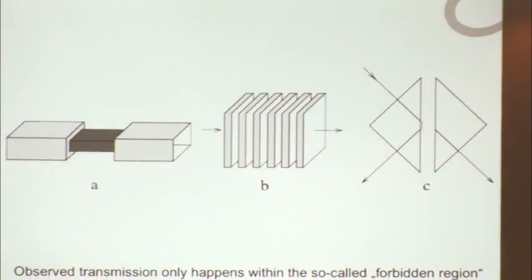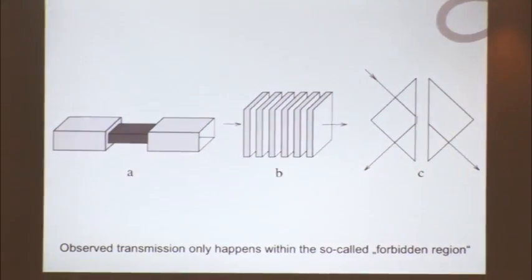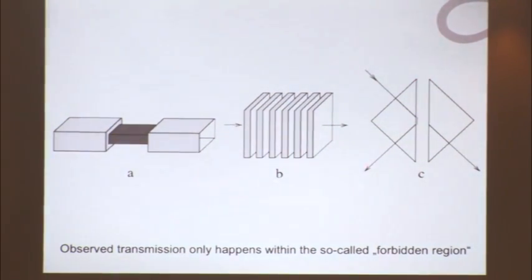As I mentioned, the most descriptive way to explain tunneling is here the double prism, but we have 2 other ways. Actually, we have a 4th one, which we might cover later on. But this is the undersized waveguide principle. So we send the signal through this one, and we want to receive it here. But within the 2 waveguides, we have a smaller waveguide. And this waveguide is, in that sense, smaller, that the passable wavelength is in fact smaller, so the incoming wave is reflected because the wavelength doesn't fit into the smaller waveguide. So we have one waveguide here, the undersized waveguide, and the normal waveguide on the receiving side as well, and this is the tunneling barrier.